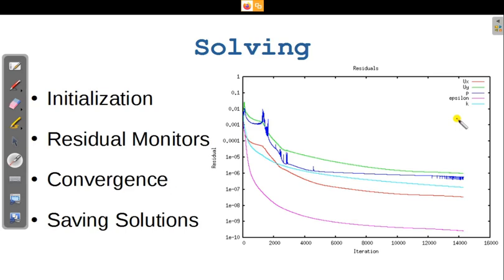The next part is called convergence. Convergence is a requirement wherein you have to bring the solutions to an exact level, stop your solver, that is the simulation, and then save your result. To reach this convergence, you have to set the residual levels. If you see this y-axis, there will be different levels from 1 to 10 power minus 5, minus 6, minus 7, something like that.